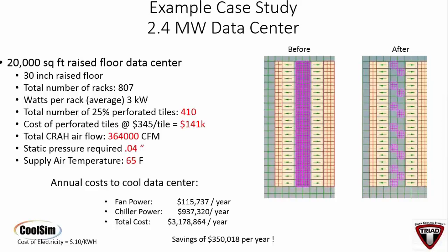So it's not about this, you want air that's presented to the servers that the server fans can use more readily and not be enslaved. And you don't need as cold air because now you're using managed fluid dynamics to transfer heat. So a big part of the Triad design is what happens inside that cold aisle, using turbulent flow versus laminar jet stream flow, which transfers heat 4 times more effectively than laminar flow will. Mm-hmm. So that's why you see the effects.